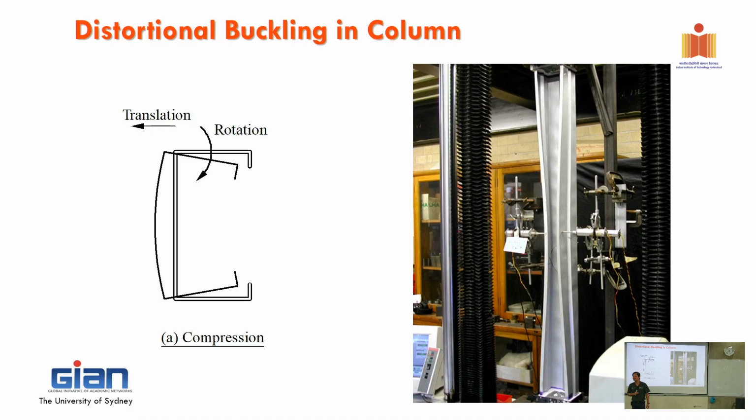So then it is the lip which plays the role in distortional buckling. How do we say the lip is influencing, or as you said geometric imperfection is influencing? Geometric imperfection just influences the shape. It can open in and out, but not the value. The critical stress is the same.